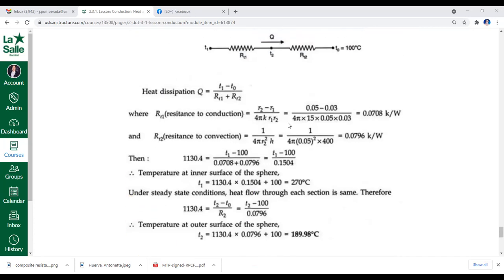So notice that you now have the outer temperature, here T sub O, and this is your T sub 2. So it's T sub 2 minus T sub O because we assume that the temperature here is higher compared to this one, because your direction of heat transfer is always from high temperature to low temperature. Anyway, you are equating here the magnitude of the heat that is transferred. If you interchange the manner of subtraction, you might as well place a negative in here, and that will make it true just the same. So this is just the magnitude of heat that was transferred.